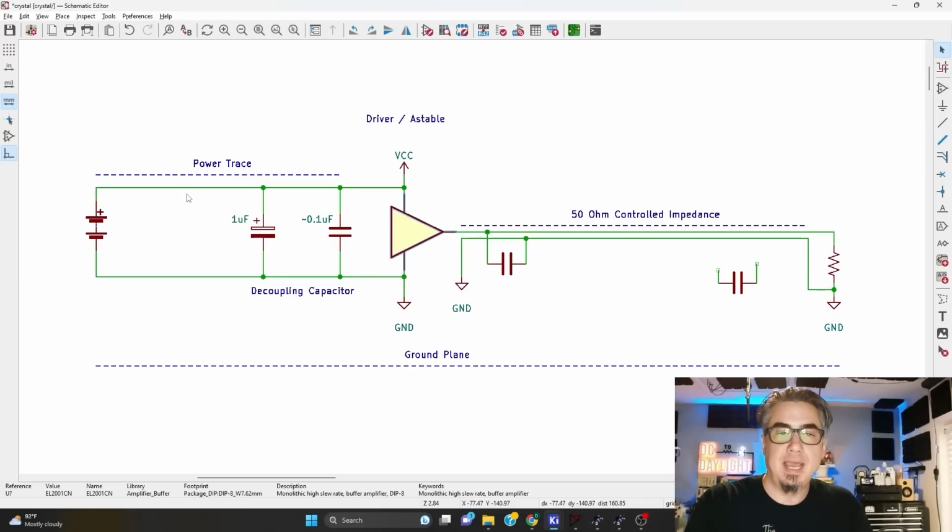So it's a good idea to have a decoupling capacitor that basically shunts across the power supply, as close to the power pins of whatever device you're trying to protect. That way, that high frequency noise, remember it has a fast transition from low to high, high to low, will look like a short circuit. The capacitor will look like a short circuit to that fast signal. Steady state signals like a DC power supply won't be affected by it, right?